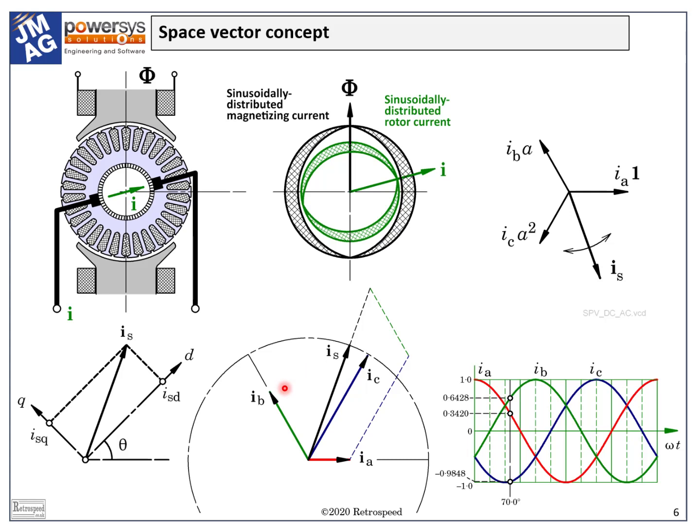When the three-phase currents follow a sinusoidal pattern, as they do in steady-state operation, it turns out that Is is fixed in magnitude and rotates steadily at synchronous speed. Now here we have the very essence of the operation of the AC machine, at least in terms of one of its variables, the current, or more precisely the fundamental space harmonic of the ampere-conductor distribution, current for short.